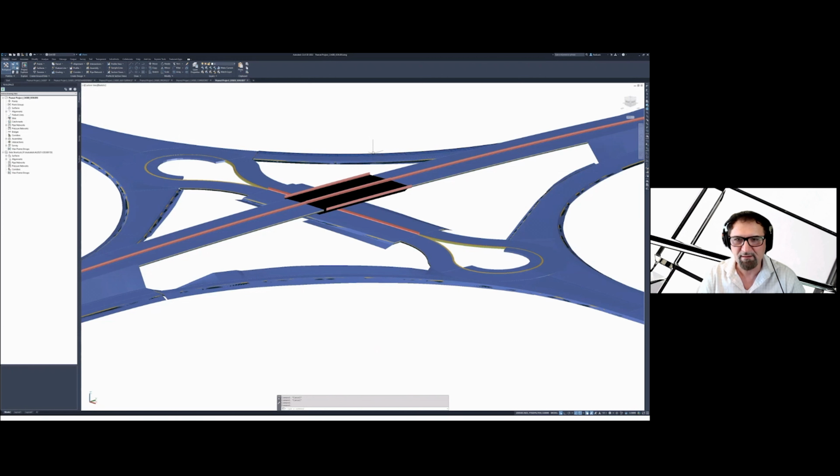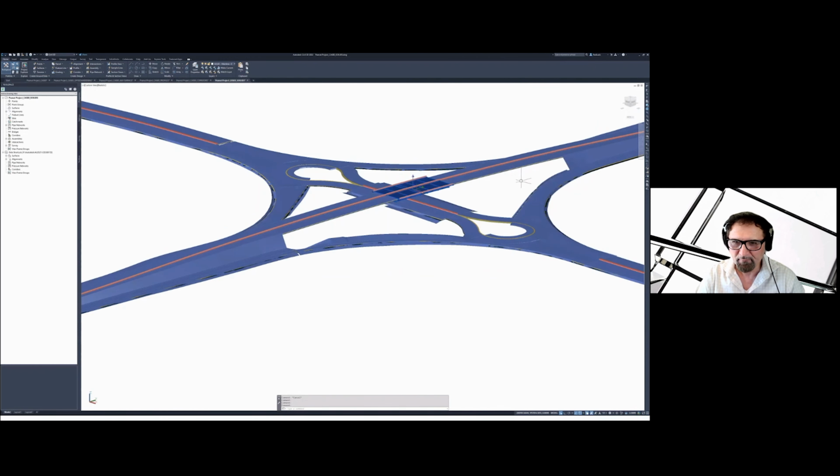I think we're not going to have time for that today. They have to be transferred to InfraWorks. And then instead of having this solid that doesn't really know it's a bridge, it's basically thinking it's another assembly. And then we can replace that part with the bridge model in InfraWorks and then send that bridge model over to Revit for final design and detailing.